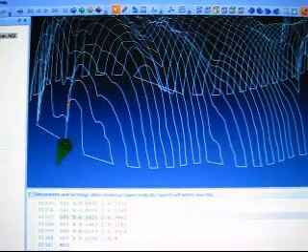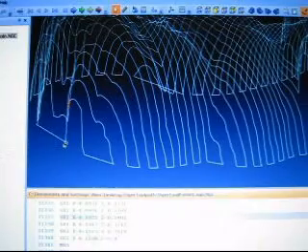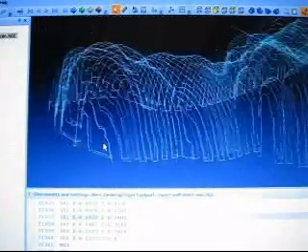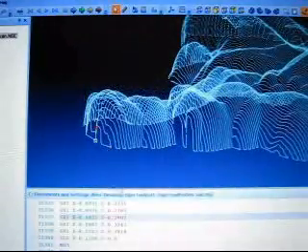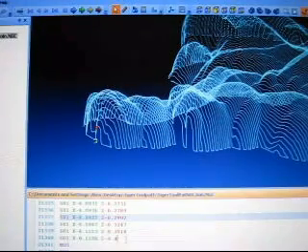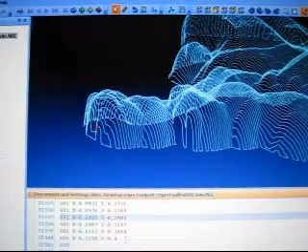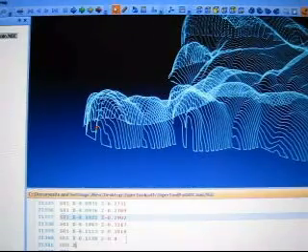The last line of code is going to be right there, and then the program's going to stop. At this point, you could add another line of code to have it wrap up to your clearance, so we can do that, no problem. So it's just a G00 Z0.1. And that's it.